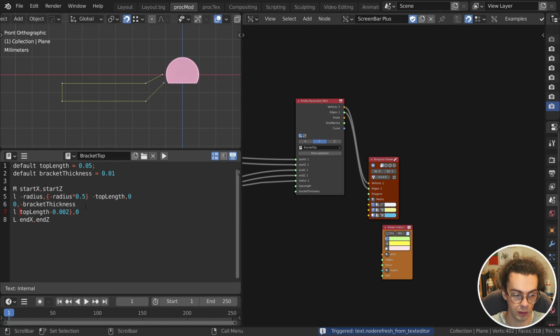So just make sure that you have it in curly brackets. Let's join that up. And then we're just doing this little clip, right? This is a top mounted monitor lamp. So it's got this little hook that hooks around the front of the monitor. So we just need to come down by 0.01, forwards by 0.002, 0 in the Y, and then we're going to go back up. So 0 in the X, 0.01 in the Y, making sure that my first one is a negative. And this has generated our little hook.